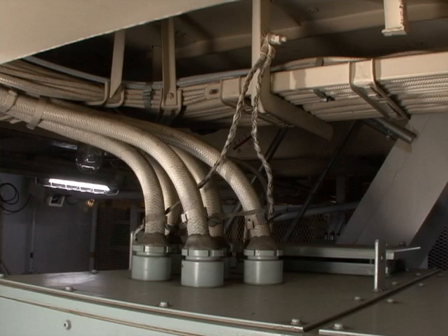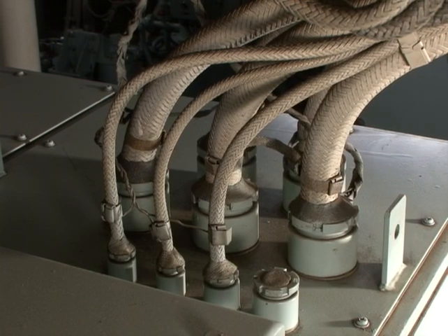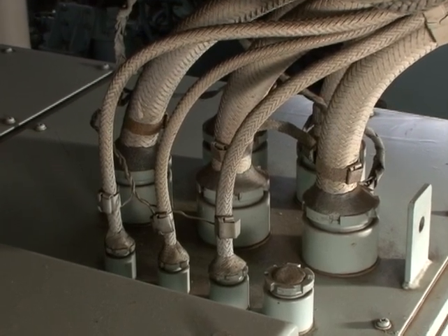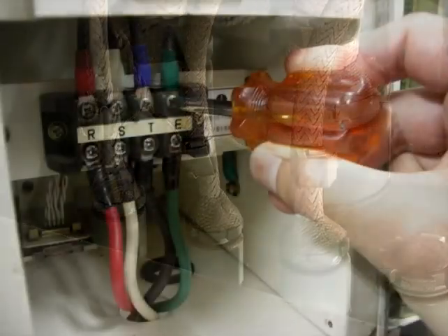When coaxial cable is used as signal wire, confirm that the armor metallic shield is properly grounded. In many cases, the part connected to the electrical equipment is grounded. Check to make sure grounding terminal screws are properly tightened.